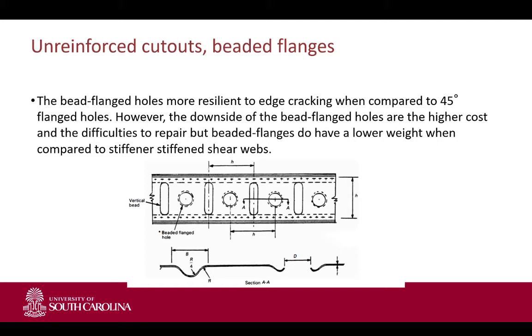And at the end of the day, everything is being validated either by a full numerical simulation, and then also validated using an iron bird test, where you basically have everything and you just break it, you bond strain gauges everywhere, and you can see if your experimental stresses are within range of what you predicted.